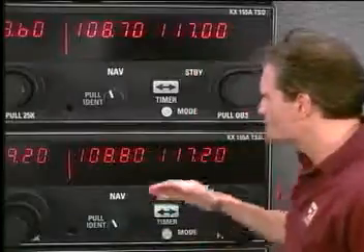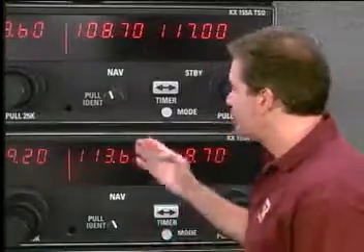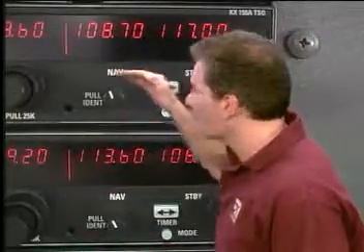Now, move down to nav2. During the approach, nav2 should be set on whatever will best help your position awareness. If you had VOR cross radials that identified fixes on the approach, you would set nav2 to that VOR's frequency. And entering the Jacksonville localizer frequency in the standby position sets you up to complete a localizer-only approach if your nav1 radio should die for some reason.